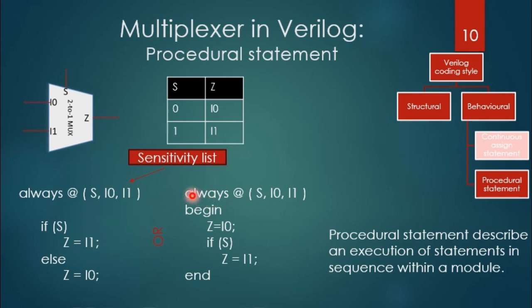So when you write the logic behavior under the always block using more than one statement, then you have to enclose the statements with begin and end. And the statements inside will be executed in the sequence you write.